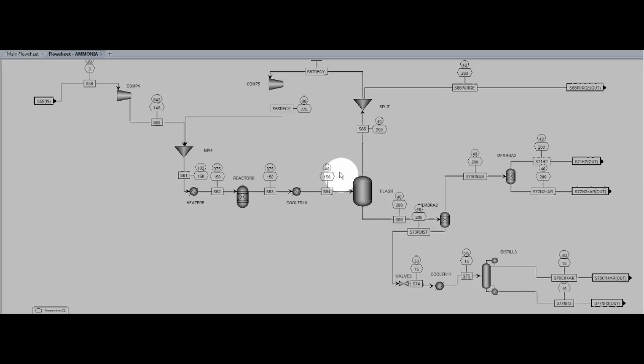Ammonia separation. The outlet stream of the Haber-Bosch reactor will be cooled down to 40 degrees Celsius and passed to a flash drum operating at 200 bar in order to recover the ammonia from this process. A flash drum model was used due to the fact that most literature sources and global chemical companies use this model to separate and purify ammonia. To purify the ammonia further to the minimum requirement, a DSTWU distillation column model was used as this provides a very good separation result.